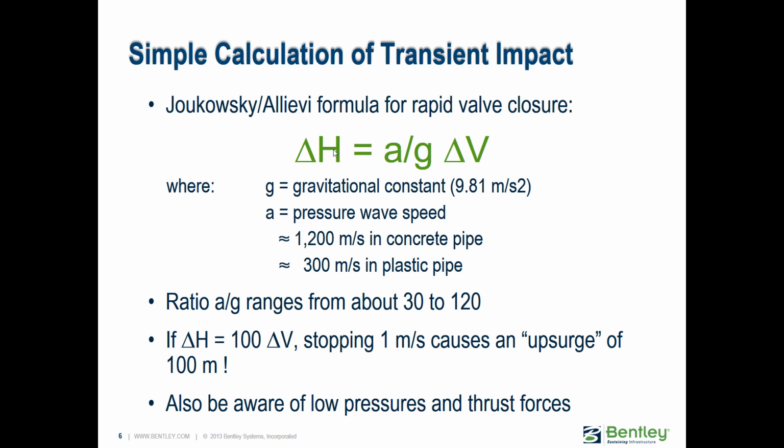When we say rapid or fast, we're talking about occurring quicker than your characteristic time, 2L divided by A. So if you have, for example, a valve closure happening that quickly, you could follow this Joukowsky equation here in green to estimate what the change in head, your water hammer pressure surge, would be, expressed in length units of head, by taking the wave speed of the pipe, dividing it by gravity, and multiplying it by the change in velocity.